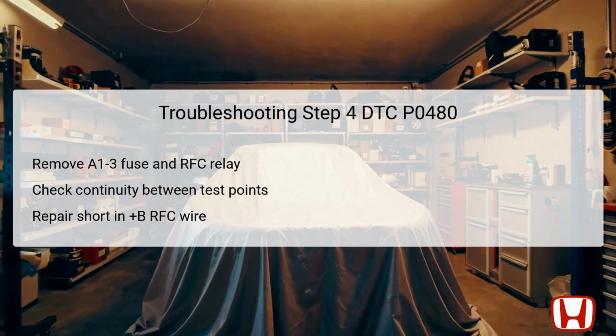Ensure that the vehicle is in the off lock mode and that the RFC relay remains disconnected during this process. If continuity is found, the wire is shorted and will require repairs. If intact, it suggests that the wire itself is in good condition, allowing you to proceed to the next troubleshooting